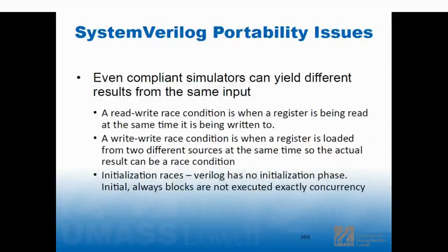And again, we could talk about this in terms of SystemVerilog, but let's just talk about this in terms of memories and how simulators work versus how actual logic works. So if I write to something and read from it at the same time, am I getting the new value or the old value? I don't know, but I'm saying you have to ask that question. So if I have a memory location, to keep it easy, and I'm writing to that location on the same clock cycle that I'm reading from it, is that output data the data that was there or the data I just wrote? I don't know what it is. It depends on your application.